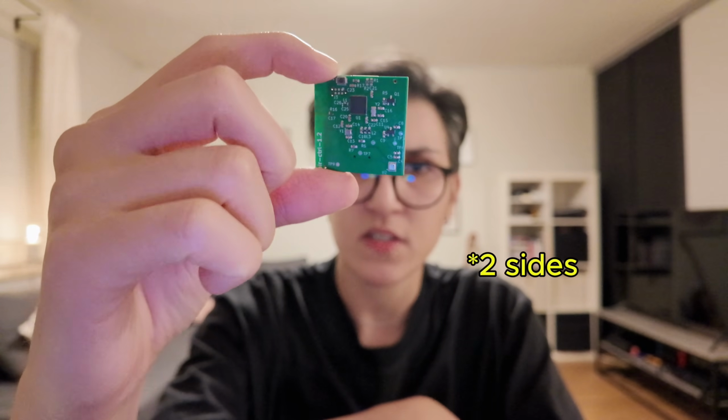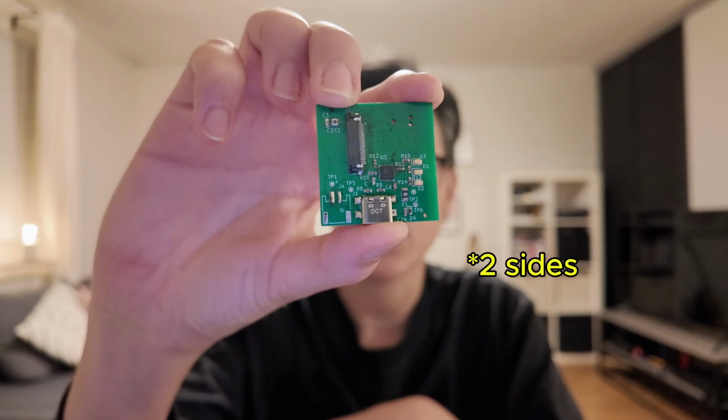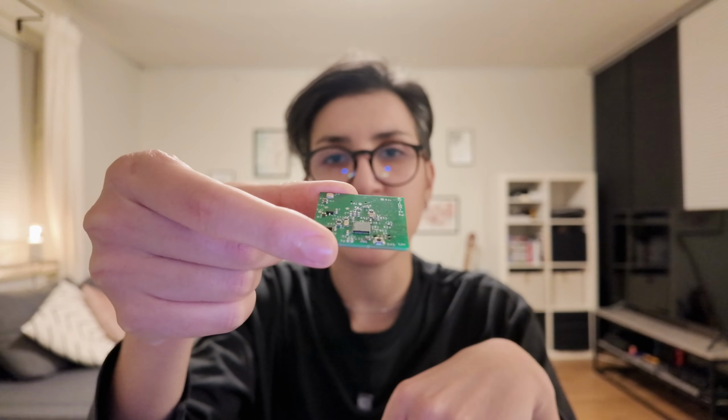The first thing that you should consider is how these PCBs are manufactured. For example, you can see this PCB has 2 layers and it has components on 2 layers. If it has components on 2 layers, they will have to assemble the first side, and then they will have to flip the board to assemble the other components. So if possible, if you have enough space, you should keep the components all on the same side of the PCB.